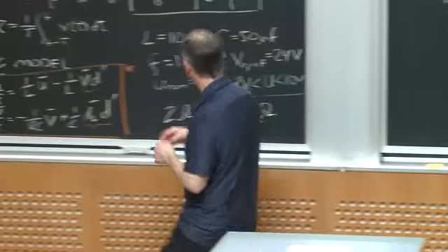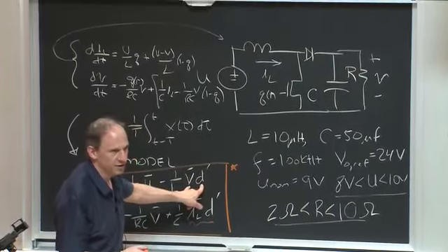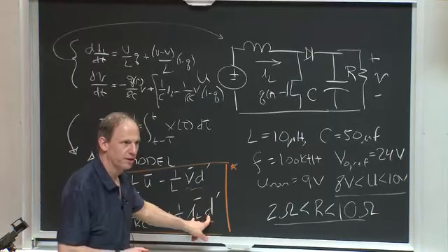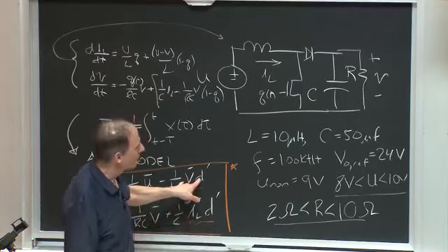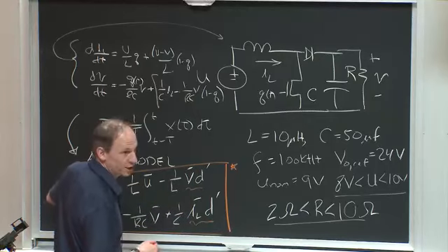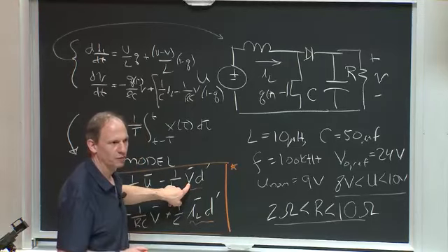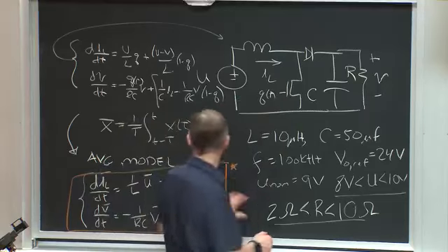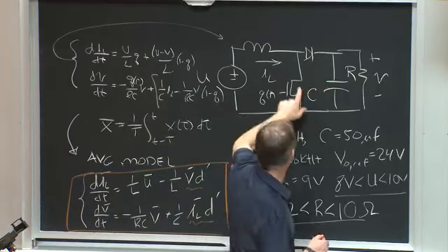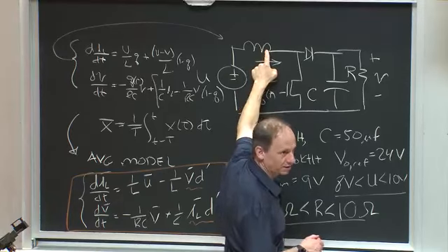It's the most flexible. So people generally would like to have a linear model for their system. So it's the duty cycle that introduces the nonlinearity? It is the fact that the response of the system has the product of the complement of the duty cycle and the voltage and the complement of the duty cycle and the current. So when I modulate duty cycle, I'm doing something that modulates how the inductor current changes, and that modulation is also proportional to the output voltage. Okay, so you can see that in here, the duty ratio and the output voltage affect how this is coming as a product. Okay.